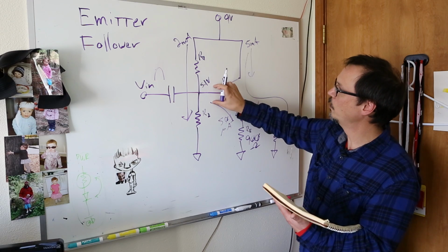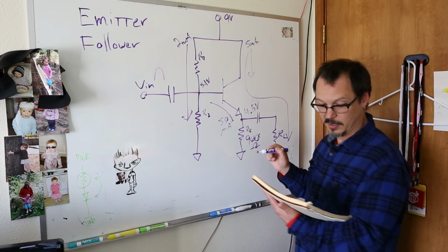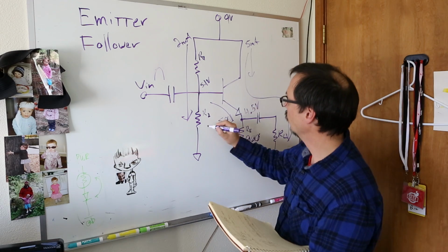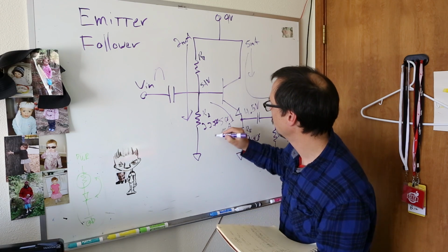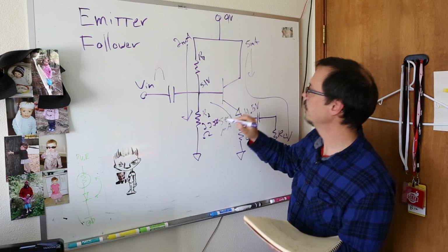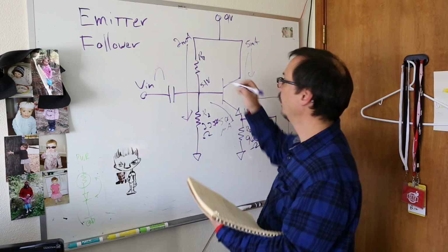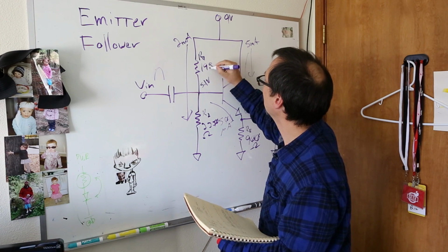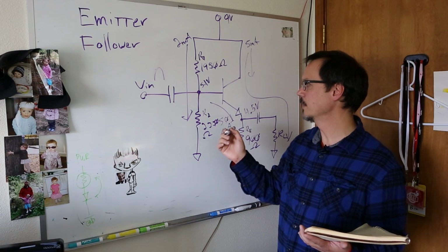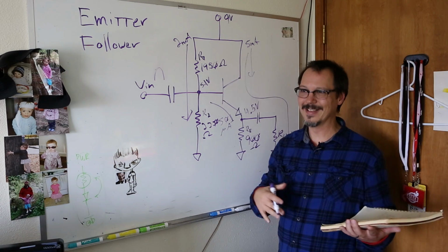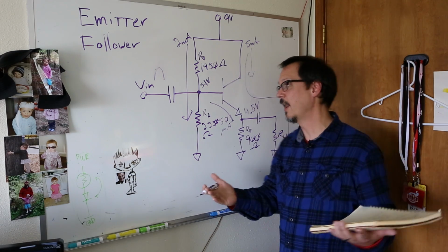To set up 5.1 volts at 2 milliamps, the numbers I got were 2250, oh, that's going to be really icky, 2250 ohms for R2, and for R1, I got 1950 ohms. As I was saying before, the input impedance on this circuit in general is considered relatively high.